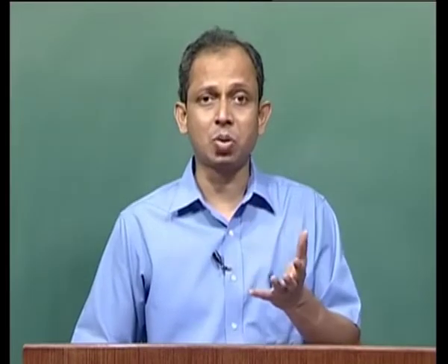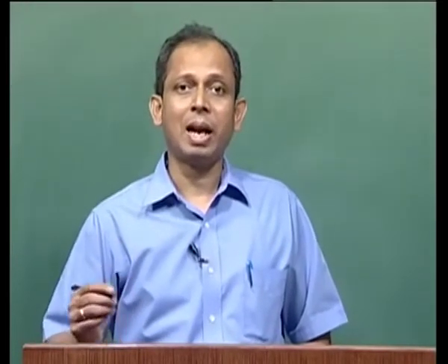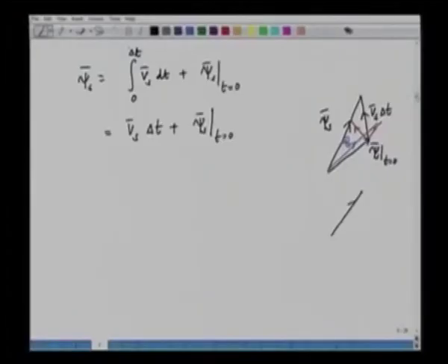So, it means we have control over the flux, and if we control the stator flux, precisely what we are trying to do, we are able to control the angle between the rotor flux and the stator flux at that particular instant, because the rotor flux has got no option but to follow the stator flux. The rotor flux in an induction machine lags behind the stator flux, because the stator flux creates the rotor flux. So, if we have the stator flux in this direction, the rotor flux is in this direction, psi r,